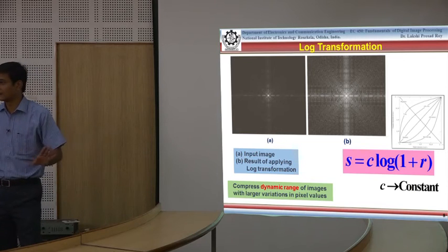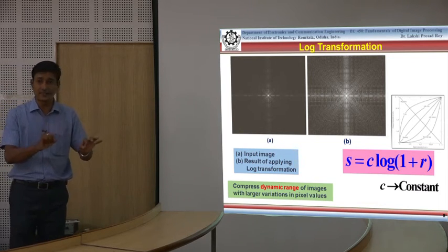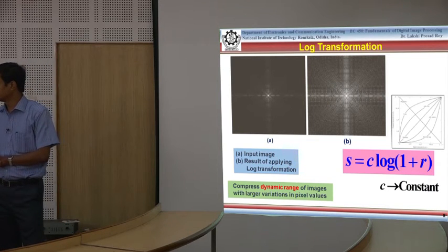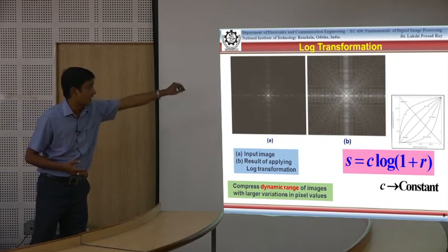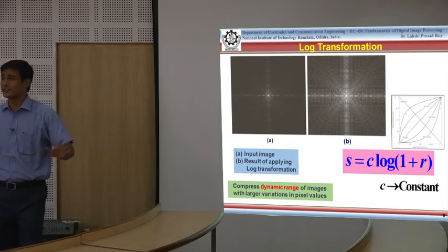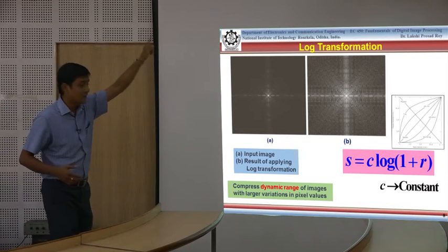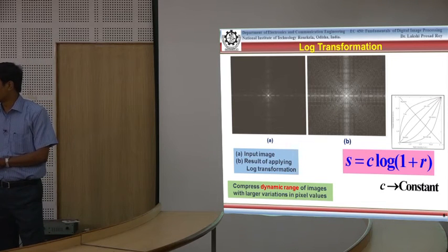Nothing is done other than this. Purely it is in your reach, you can take the intensity values and do this operation, and you will get the image output that way. Now, you see, a small operation of this kind has made the image completely different from the earlier one, where the bright portions have come till the corners of the image. How could it happen?